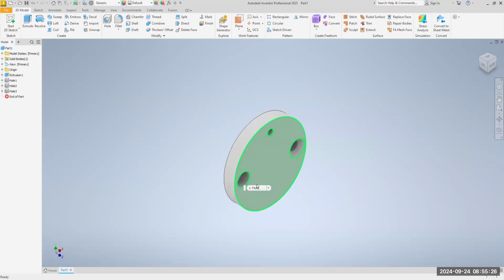Talk a little louder, Potter. So it doesn't stick out. So it could be a trip. You might have something sliding, one surface sliding over top of another one, right? So you don't want the head of the bolt sticking up, because the bolt is also a trip hazard if it's on the floor. A lot of times, if it's something related to the floor or the walls, you definitely want to counter bore the screws.